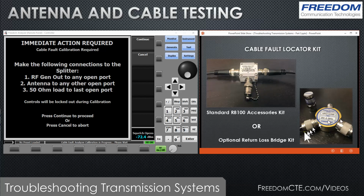If you have our optional return loss kit, or you have your own other splitter you can use, this is a picture of the one that comes with the return loss bridge kit. And these are all N-type connectors. That kit also comes with cables that fit it, and also there's an N-type 50 ohm load. Once you've done that, you simply press continue,